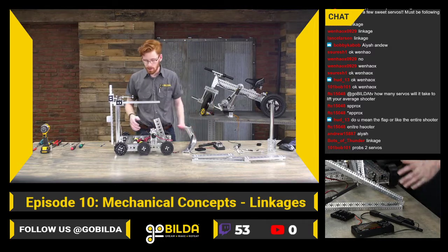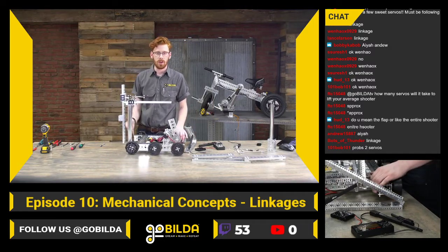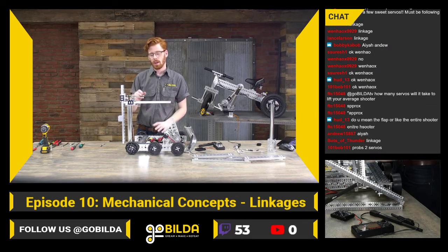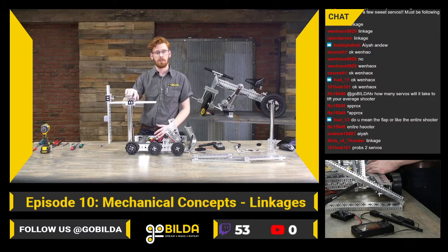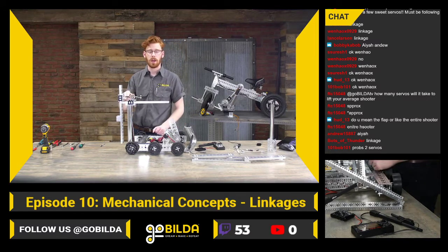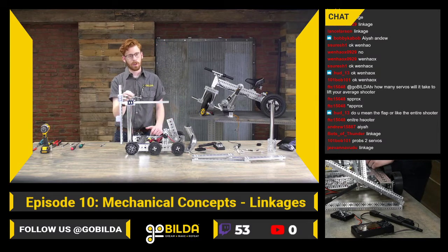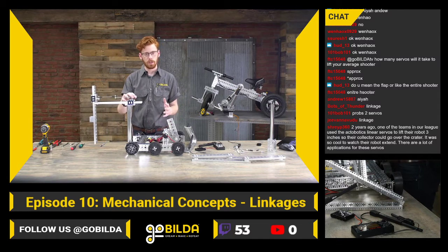One big thing that I've seen some FTC teams do in the past that I really love is what's commonly called zero load claws, where you've got a claw system that's run by a servo, and you want that claw system to have no load on the servo while it is clamped down. This is really nice because you can use a really, really fast servo and not worry about stalling it out or burning it out. This is a great example.